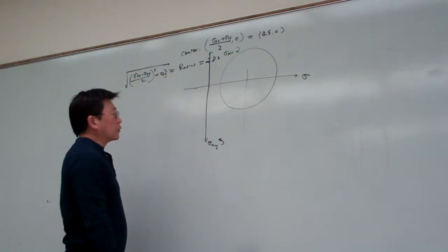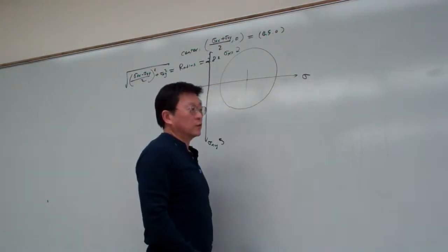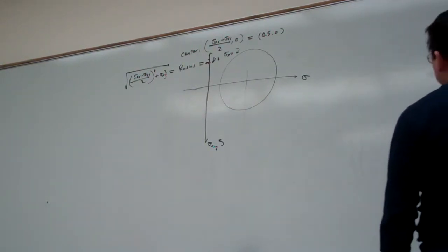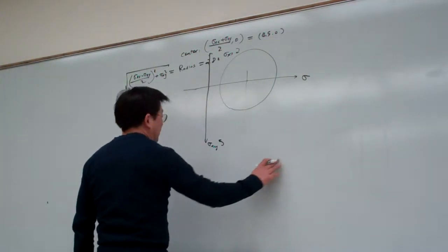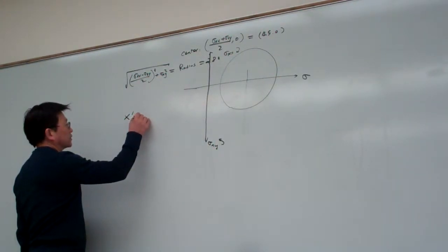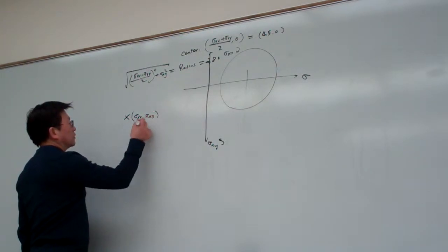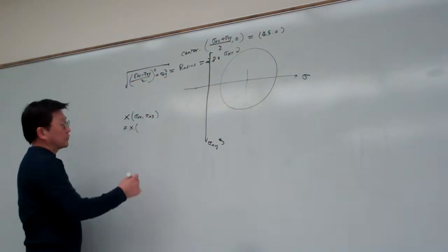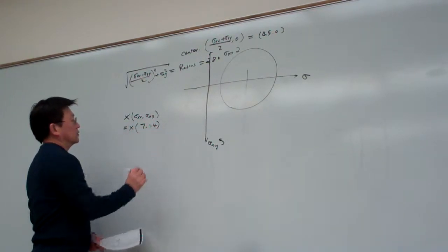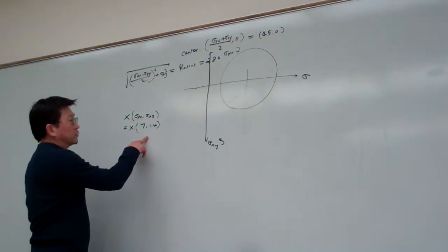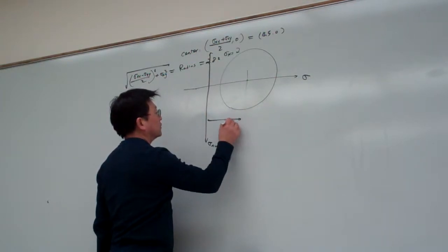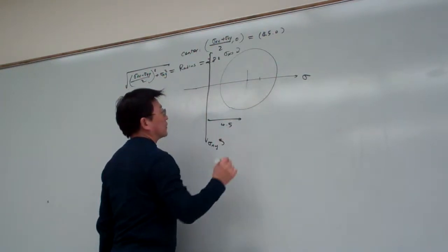Okay, and now on the Mohr circle we want to determine the principal directions. So in this case, we have to label the status of the point on the x-plane. The x-plane constitutes sigma xx and sigma xy. So the x-point is sigma xx equal to 7 and 1.4. Okay. So this is the X point, located at 7. This is 4.5 here, so 7 will be about here.